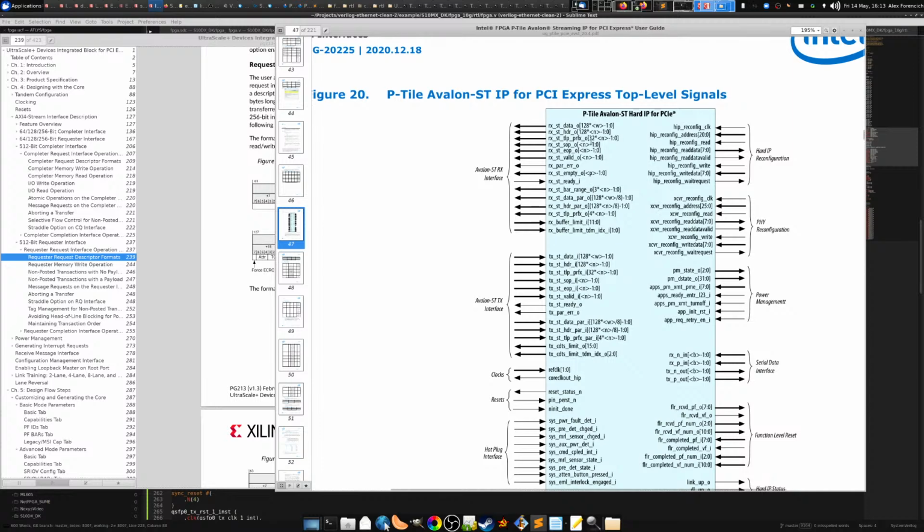And it also has the effect of kind of widening the interface a little bit because you have an additional 128 bits just for moving the header. And that's rather important when you're trying to run at, you know, Gen 4 speeds where it's like 256 gigabits per second. You're going to have a hard time dealing with all that data. So if you peel off the header separately, then maybe you can run at a slightly lower clock speed and still get a sufficiently high throughput.